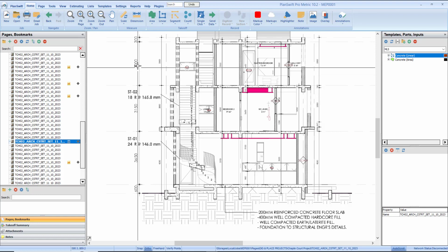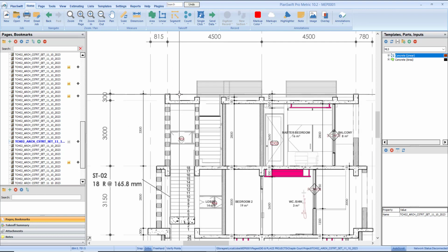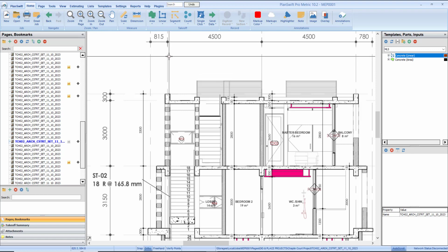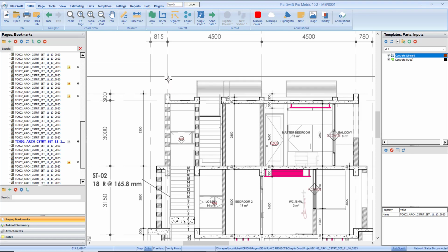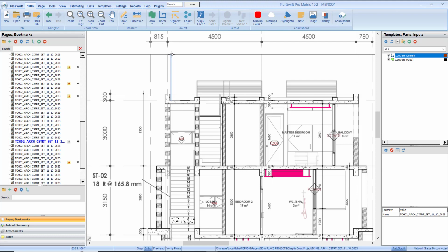3.15 meter, 3 meter, and then we're going to have our water tank at this level. It's not going to terminate at this point where we have this 3.0 meter. It is going to go all the way to the height of that tank. So what would determine the height? We're going to add, from this point to the place where you're going to have that tank, the size of the tank, and you can also check your drawing to see the details of the water tank.